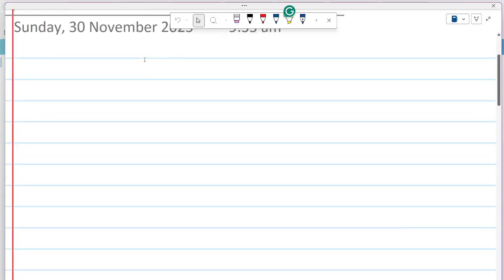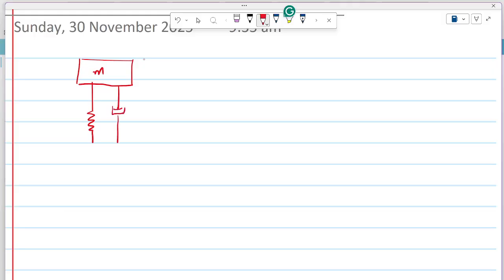So let's suppose you have the mass spring damper system. You have the mass here, and you have a spring connected to the ground, and you have a damper connected to the ground. It is being excited, with a free vibration, and let's call this the positive x-axis. It is a mass under free vibration. So you can draw the free body diagram of this one. The first step you take is to draw a free body diagram.